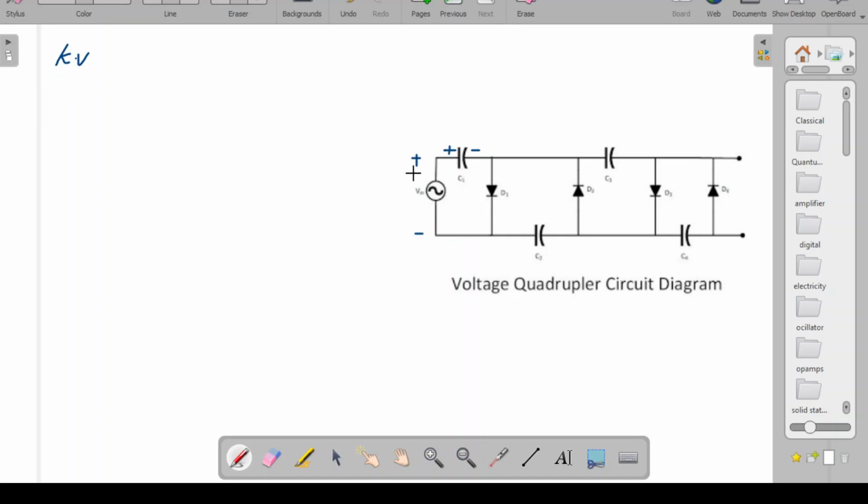Conventionally, we can take this voltage source Vin as positive, then this is negative positive, so this has opposite polarity, so this is minus Vc. If I take the capacitor's charge as Vc, and there is no other voltage source or voltage drop, I can say this is equal to 0.